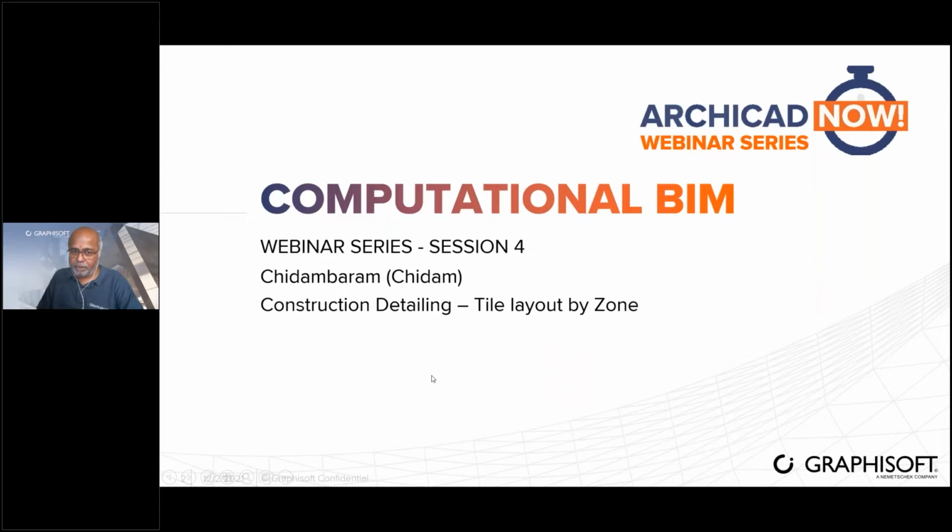Today's session is some useful stuff we are going to share. We will be sharing construction detailing. We are going to show how you can do tile layout from a zone object, right? So normally we place rooms in Archicad, which is actually the zone, but use that as a boundary and create the tile layout inside. So this is more for construction detailing, right? So you want to know how many number of tiles and all those things. So this is what we are trying to achieve today, right?